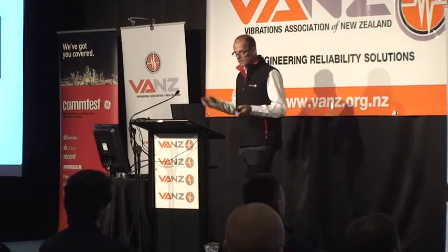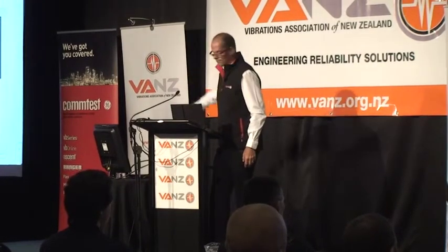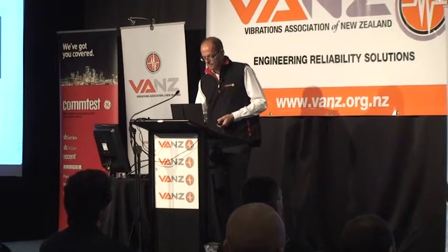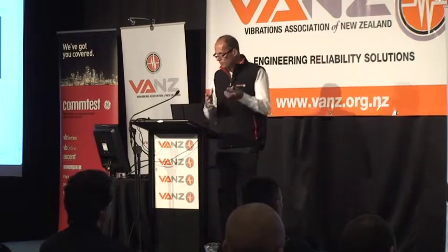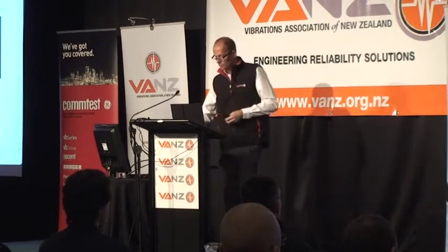And here's a real example. So there's the gears there, and you can see it on both sides, obviously, and you can see the damaged area just here. And because there is that damage, when that goes through the mesh, we see this spike.